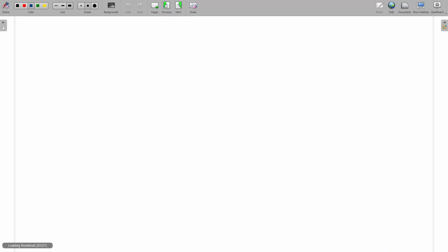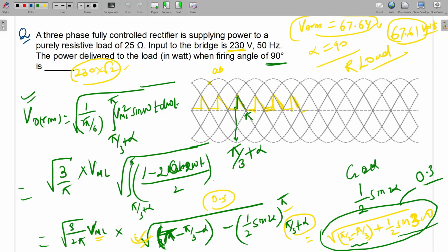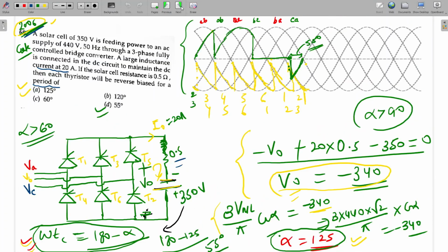So see, previously all the sequence what I have taught, that same thing will work. You can verify with the circuit. Like here, normal phase sequence is normal ABC. So this time I'm starting with AB. I'm starting here. This is waveform 6-1. So 6-1, 1-2, 2-3. Again it will repeat. So you can see with the circuit also. It will be same.